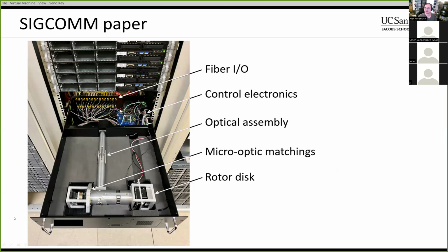So I'll just show you guys a little picture of the test setup here. This is the optical switch connected to some of the hosts that we have in the rack. So we use 16 hosts with, like I said, the combination of FPGA boards. Those are hooked up to the fiber ports in the back. So we've got 32 MPO connectors here. Each host gets 2 cables. So there's eight uplinks per host. And then this here in the front is the optical switch.